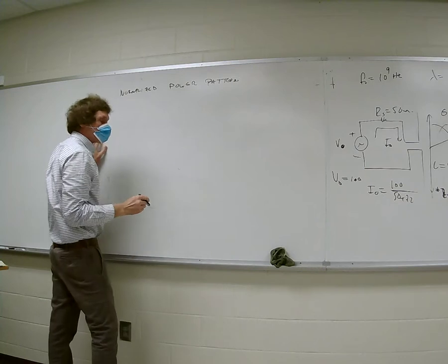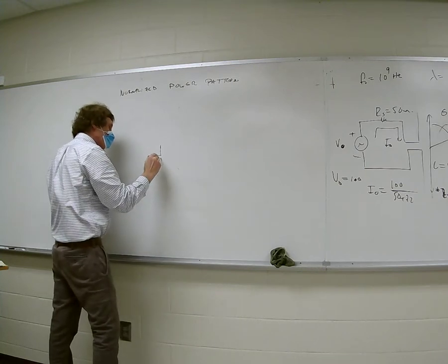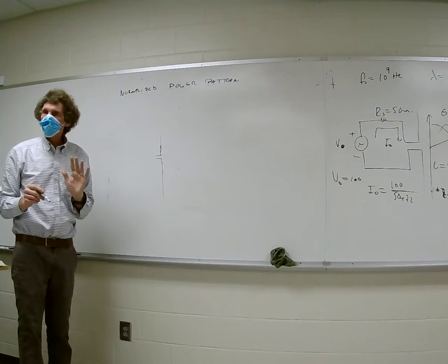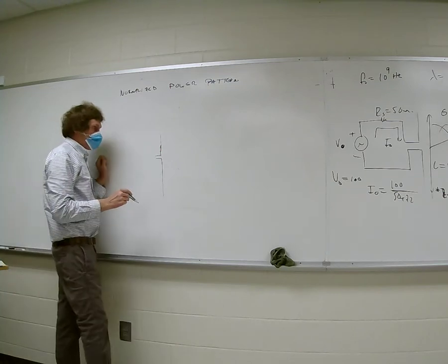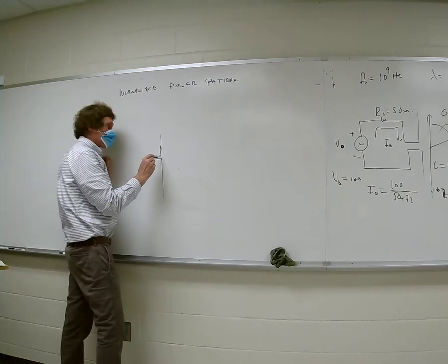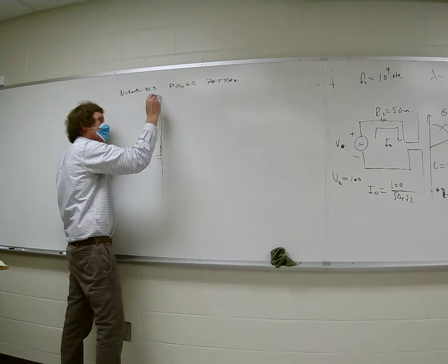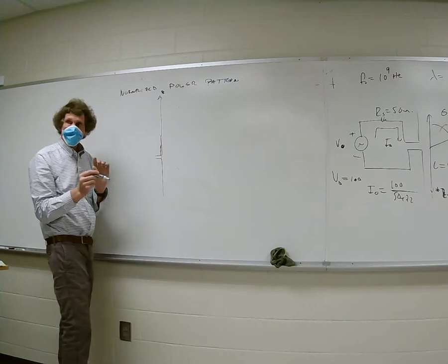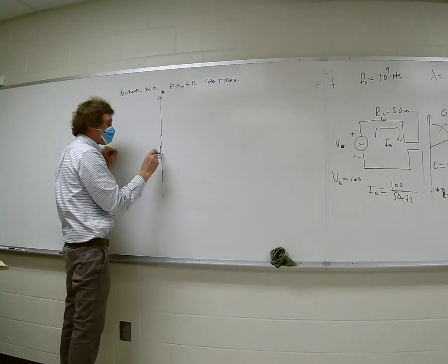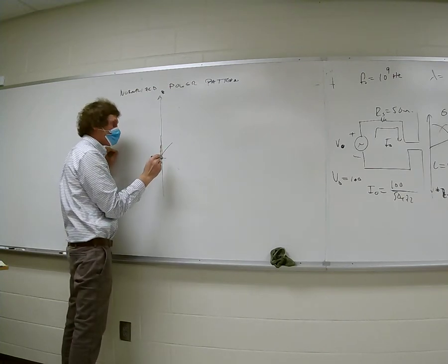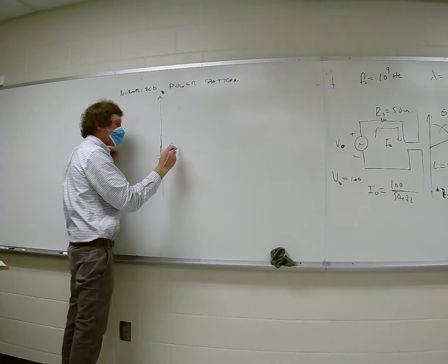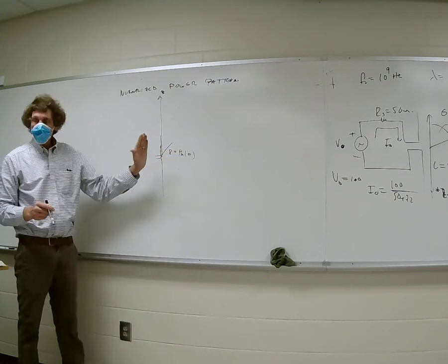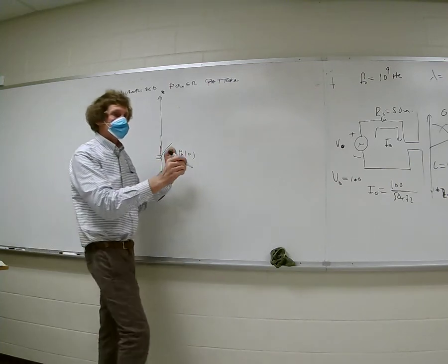So what I'm going to do is just show you an antenna like this. What they normally do is plot it in spherical coordinates. They're going to have the antenna up the z-axis, so it's aligned this way. Don't worry about the length of the antenna. And what they do is plot a radius vector where this vector r is actually equal to the normalized power density, okay? So if you look at the normalized power density for a short dipole,